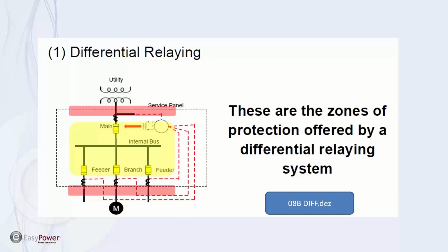And so the hardware that's being presented basically has a fusible switch that allows us to detect the fault and then open up the switch quicker than the fuse that's installed can respond.